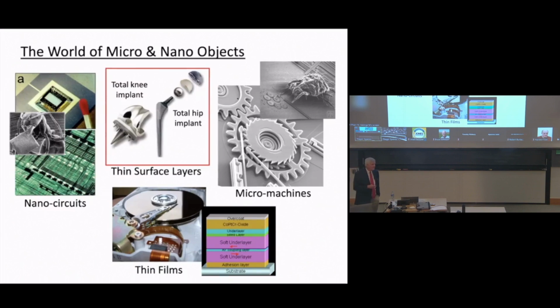And so occasionally the head comes into contact with the magnetic layer, or with the disk. The magnetic layer is extremely soft. And if it weren't for a hard overcoat on the top of that, you would destroy all the information on the disk if you happened to land the head on top of the disk.